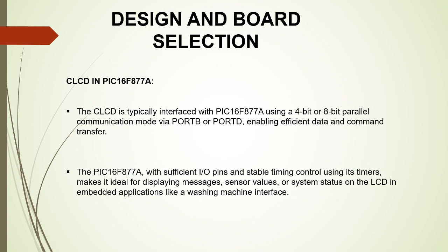CLCD in PIC16F877A. The CLCD is typically interfaced with PIC16F877A using 8-bit or 4-bit parallel communication mode via port B or port D, enabling efficient data and command transfer.